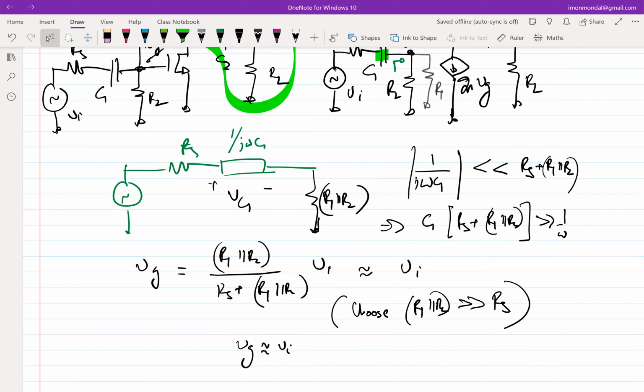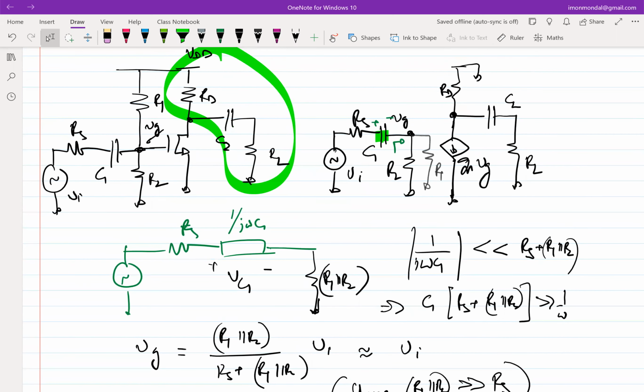What I have done, mathematically, is simple algebra, right? But I want to drill in the thought process behind it. So what is the first thing? The first thing is, we cannot do away with the capacitor C1, because we wanted a floating battery, which we cannot have. So we replaced it with a capacitor. A large enough capacitor acts as a battery.